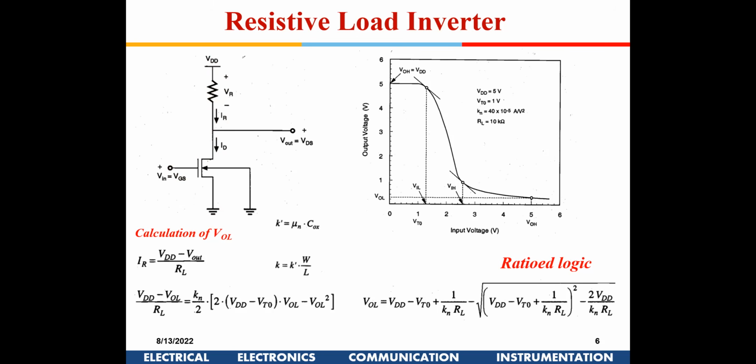That is not leakage current. Yes, that is the on current of this transistor. By design, the on current is static current here in this particular circuit. But when you explain the CMOS, that is leakage current.